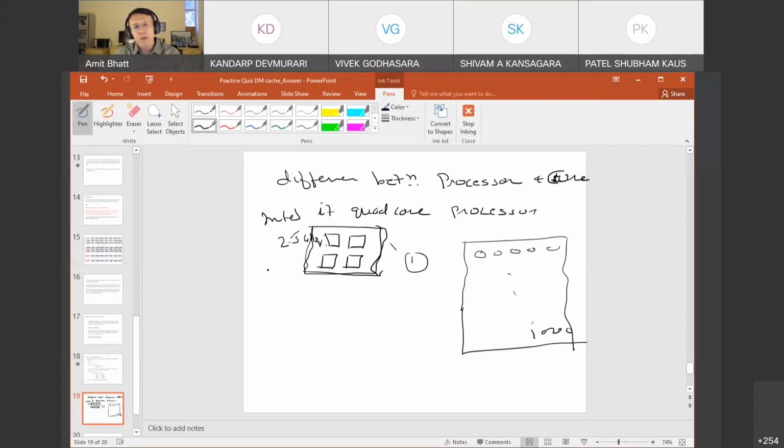You'll see that your processor gets heated up to 100 degrees centigrade. Actually, if you touch the processor's small IC, not the casing, but touch it inside, you'll burn your fingers. It gets that hot. So if you try to jack it up, your chip would burn up like that, right? So if you have a processor which needs to service a single task, which is not parallelizable, which is serial, and if you want to do it fast, then you have to have a processor which is very fast, meaning more frequency.